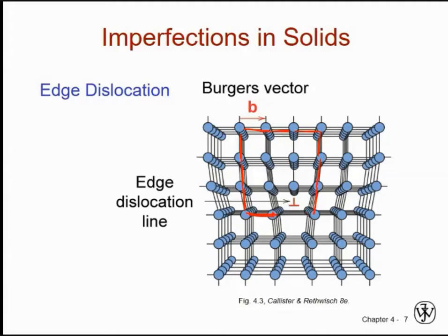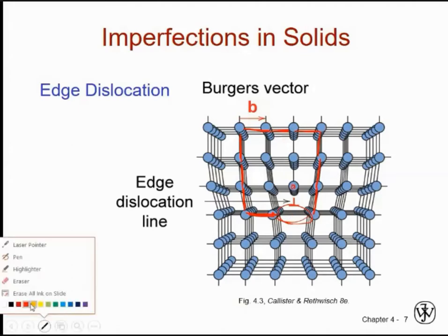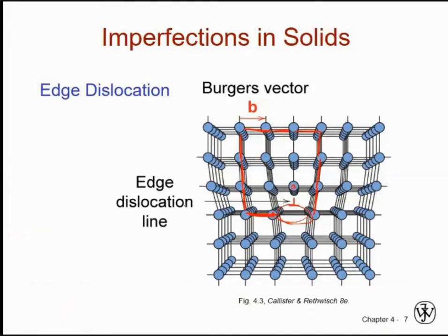And if you see, I have this open space over here. I can join this because this half is missing. And how can I join this one? In order to join this, I can draw this kind of vector. This was the start, and this one is the finish. I will connect start with finish. That's it. And that is the Burgers vector magnitude and direction.